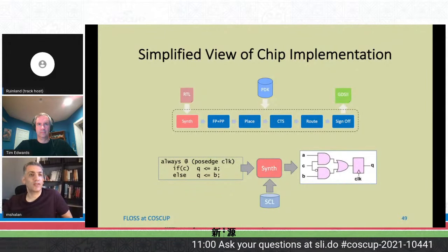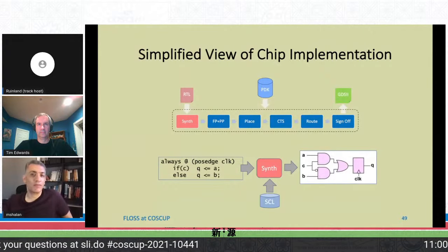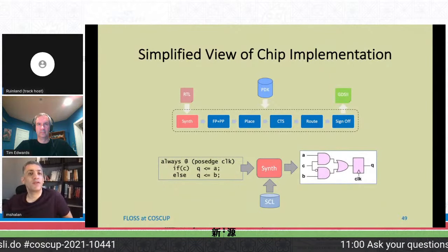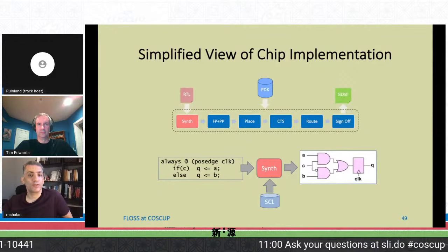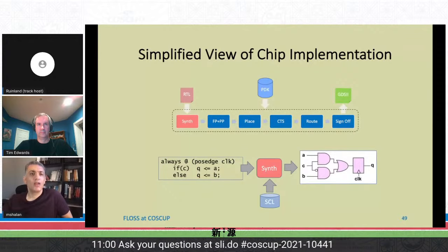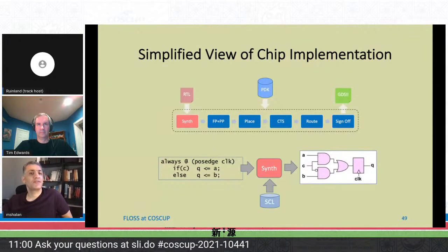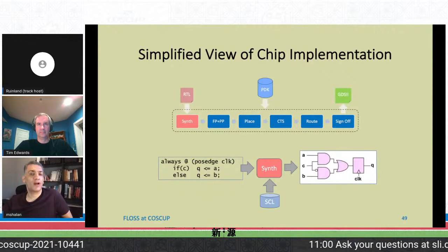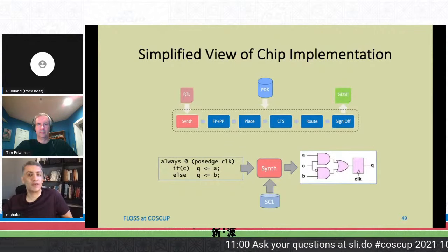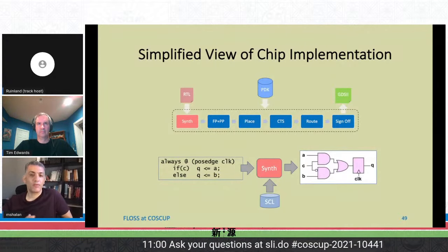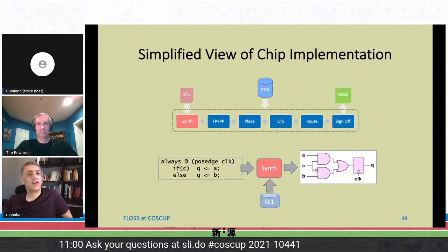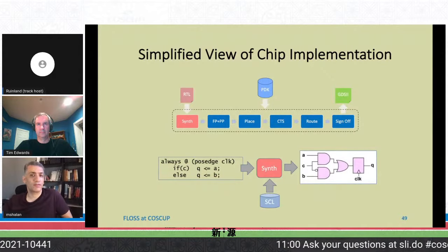This circuit is made out of components from a library of pre-designed, ready-to-use components that we refer to as cells. The end result of the synthesis is the gate level netlist, which is also described using hardware description languages such as Verilog or VHDL, because any HDL allows the description of the hardware at different abstraction levels.